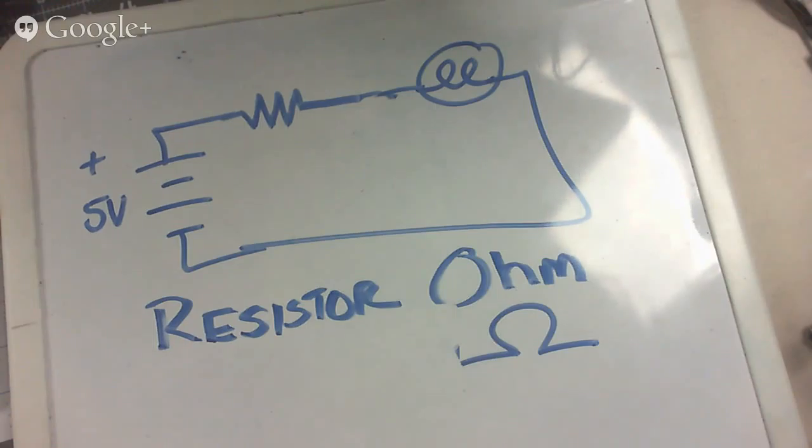If you have an application that requires a very precise resistor, you'll have to add resistors together in different combinations. Usually it suffices to say that, say you calculate that you need 213 ohms, then you go grab a 220 ohm resistor, you'll be fine. That's where electronics is more art than science. So that's why you prototype stuff.